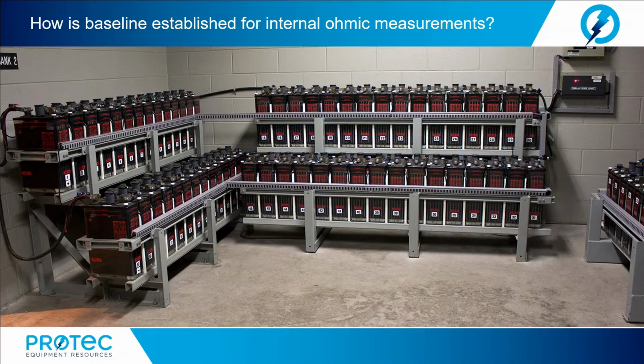So, to resolve the problem of the unavailability of baseline internal ohmic measurements for the individual cells or units of a station battery, many manufacturers of internal ohmic measurement devices have established libraries of baseline values for VRLA and VLA batteries using their testing devices.